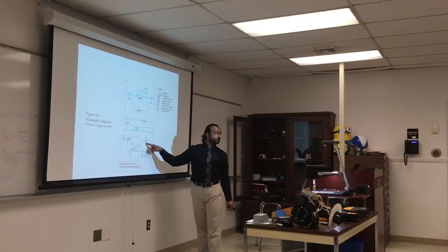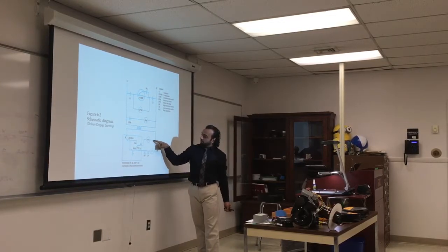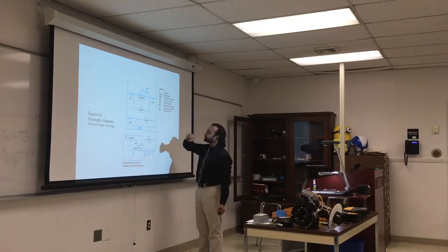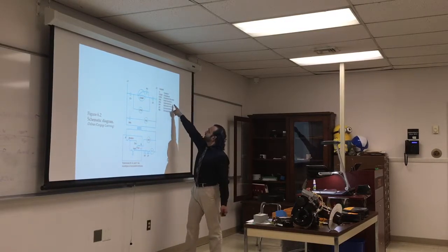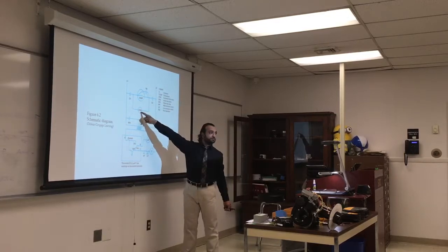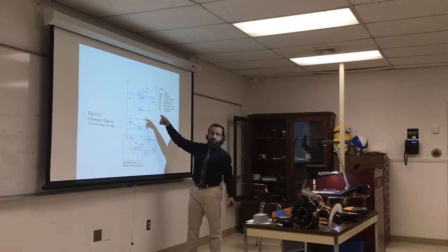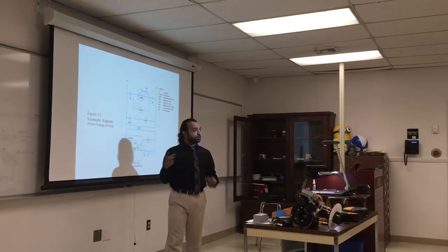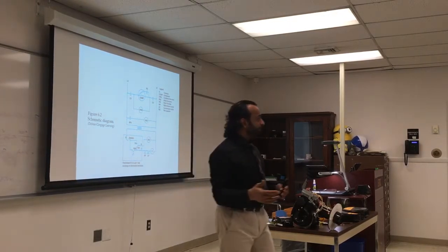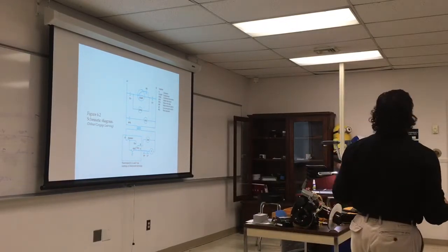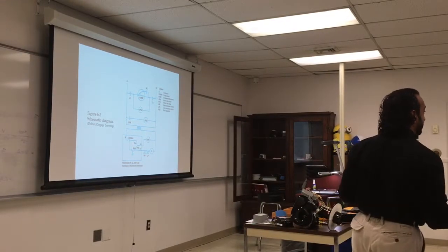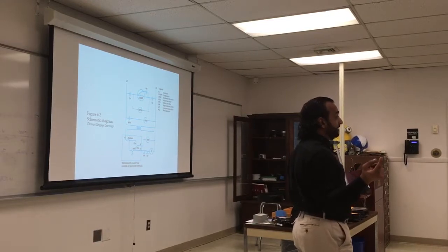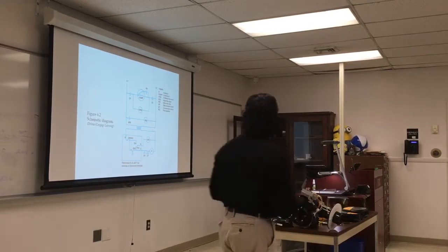Indoor fan relay? There's a relay here. It's controlled by the thermostat. And here we have a condenser fan motor for the outside, so the air will come out. Indoor fan motor. For any AC, there are two fans, one inside and one outside, and it's separated. It's not only one fan. In the window AC, it's different. There's only one fan to the inside, not the outside.